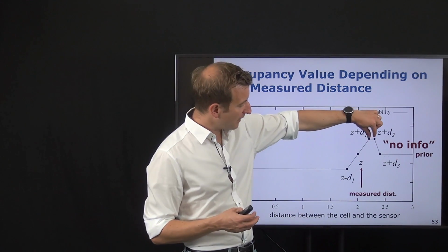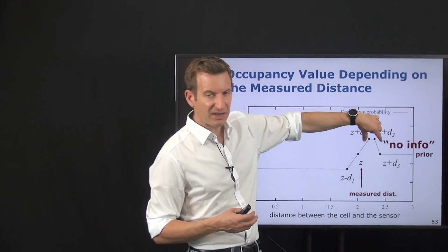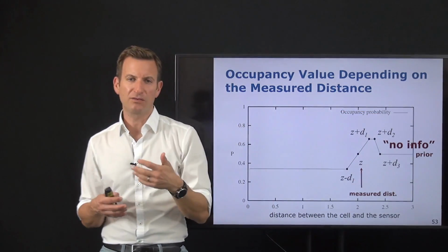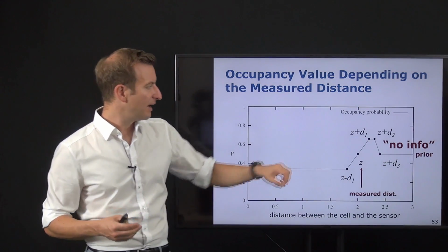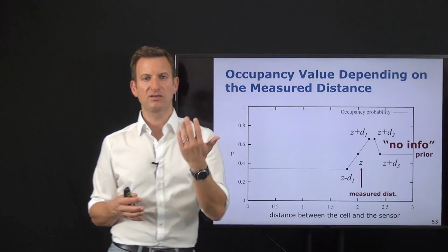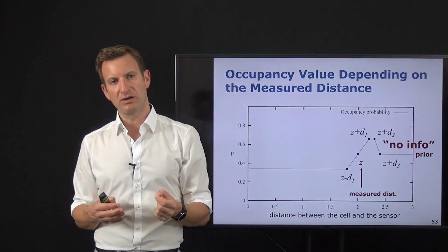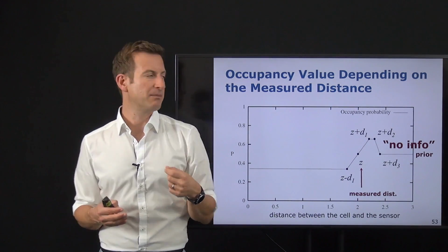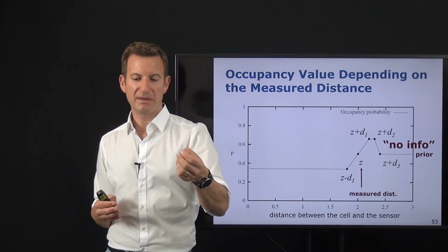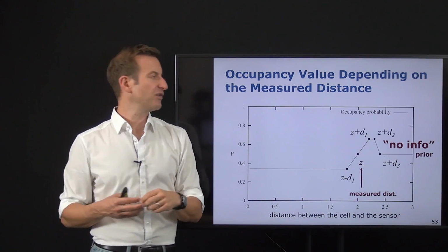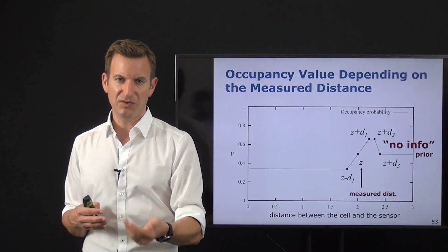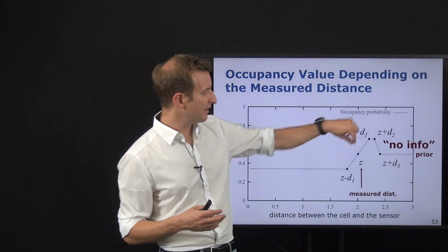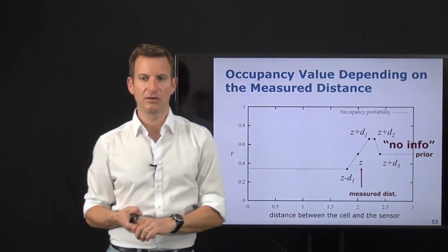And again, how thick, how many cells I'm updating here is basically prior information, an assumption about how thick my walls are. And I need to have a certain thickness over here because the sensor is so noisy. If I just have very, very thin walls, the number of times I'm actually reducing occupancy probability would typically override the points in time where I'm seeing an occupied obstacle. And therefore, I have to generate a certain thickness over here.